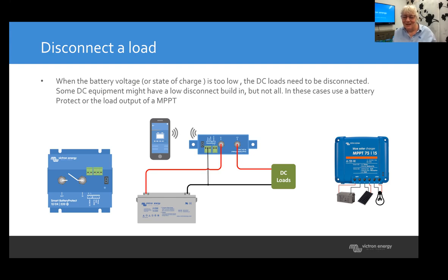Talking about boats, especially even if it's in a marina, not on a trailer under a carport or something, invest in a small solar panel just to keep your batteries charged when not in use. Should something happen to the power, if it's on an unpowered mooring or something like that, put a little solar panel in just to keep your batteries charged. Self-discharge happens, stuff happens. A boat is always partly live because you've got bilge pumps and other things that stay on quite often. So those are some hints and tips.